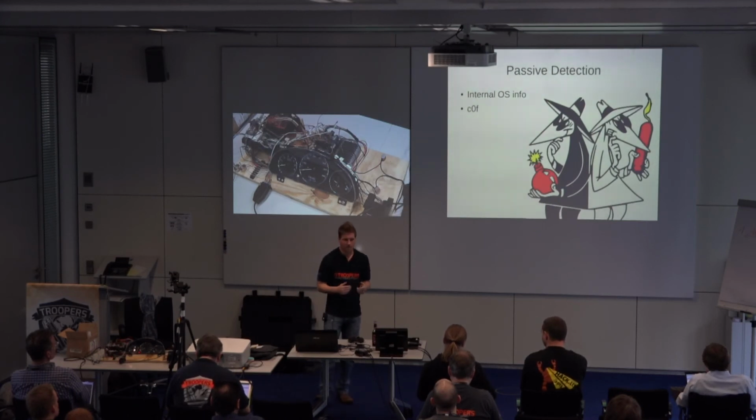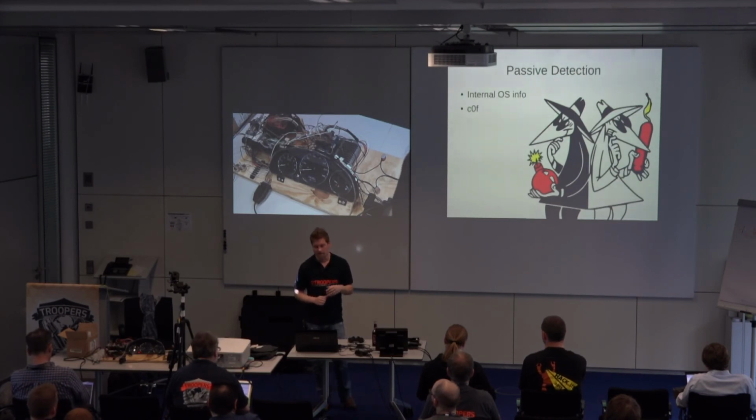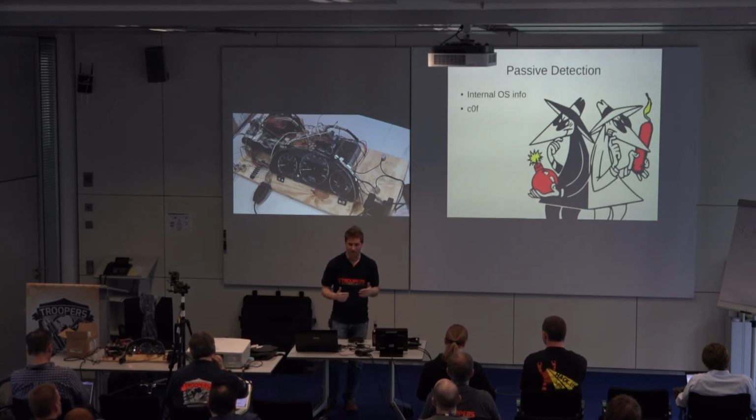The thing is, you don't want to send packets, because these parts are used in a bunch of different vehicles. That ECU is used in a ton of GMs. That Honda navigation system I had was also used in a bunch of pickup trucks. Sending the packet that you think is going to control brakes may not do it in the other vehicles. So you really want to get a baseline.